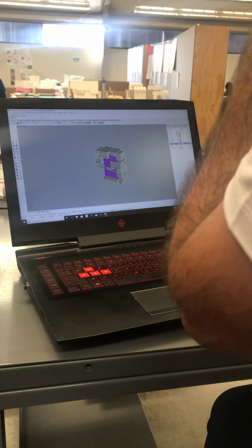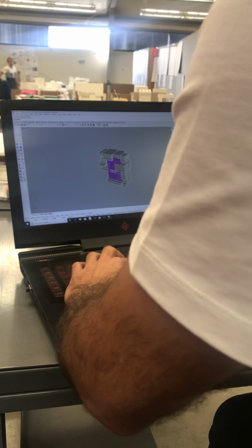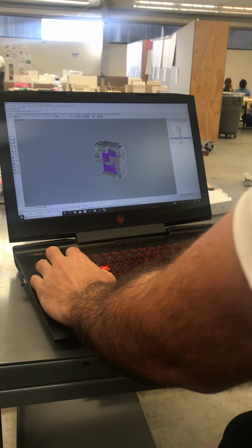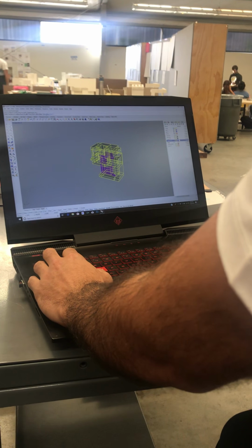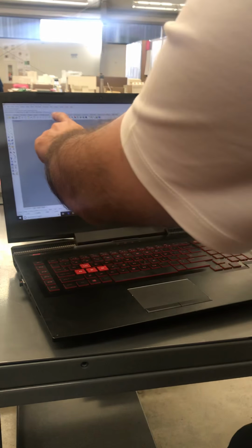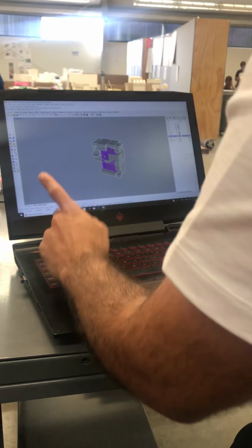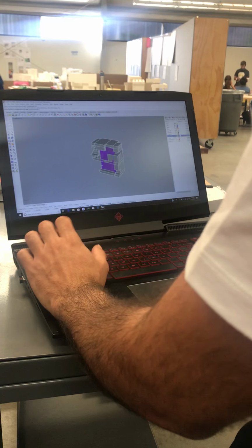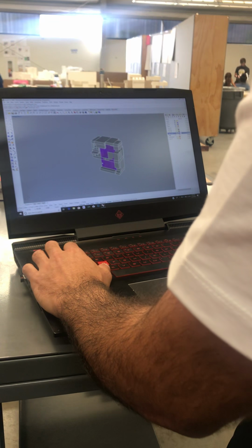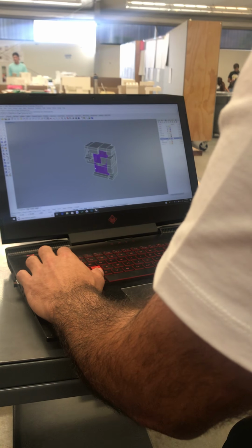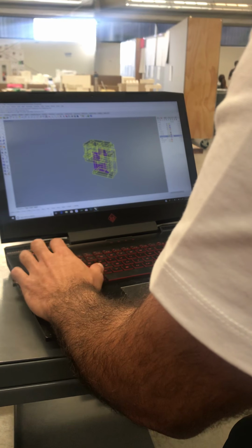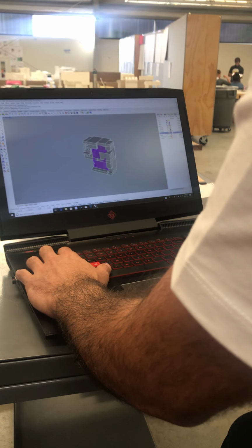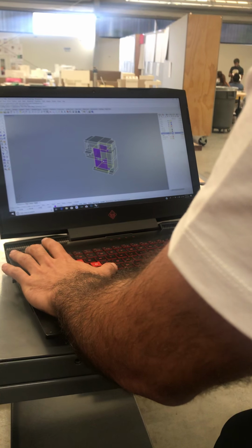Okay. So to do my crop, you guys already know, you use Boolean split. Select surfaces and polysurfaces to split, so I'm going to select this one. And then I'm going to change this delete input from yes to no, so that it doesn't delete input. It just keeps my model and just makes 2 new split things on top of it. And then it tells me to select the ones that I'm going to use. Split, I'm going to select that, and then select cutting surfaces or polysurfaces. So then I'm going to select my subtraction box.